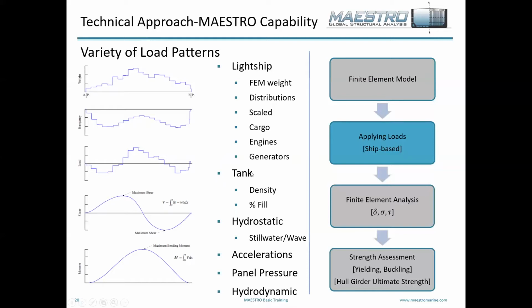For tanks, you model the individual tanks as a volume group, and once you've got that volume group defined, you can then fill the tanks by defining the density of the fluid that's in there, as well as the percent full. There are other methods besides the percent full. You can also give it the mass and the density, and it will determine, based on volume, how full the tank is. But you're essentially modeling tanks in the traditional sense. You have a volume, and you're just filling it with a liquid of some density.